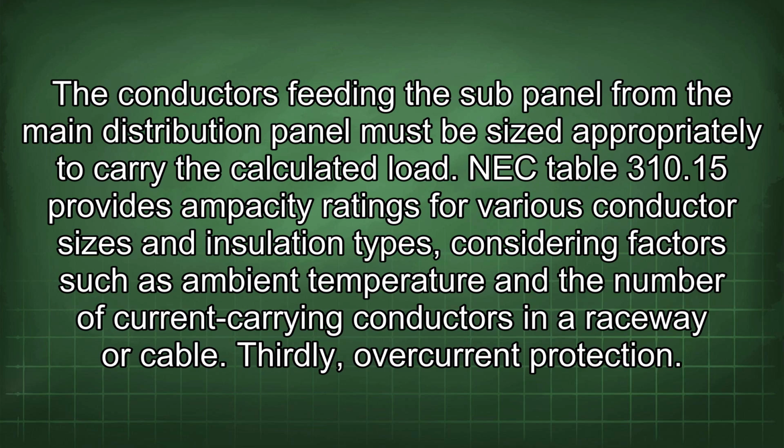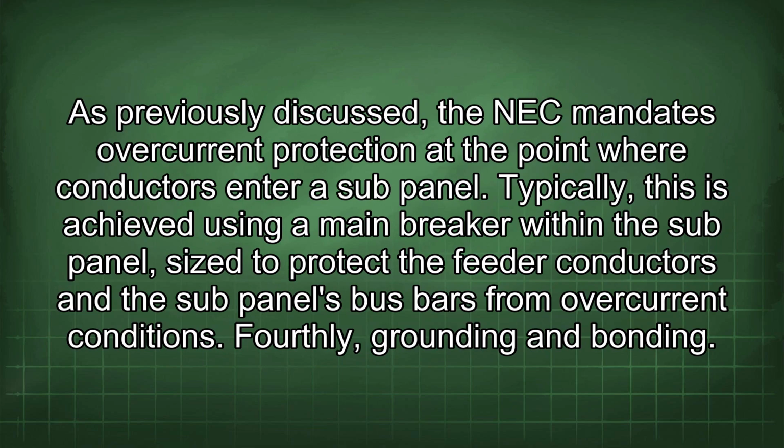Thirdly, overcurrent protection. As previously discussed, the NEC mandates overcurrent protection at the point where conductors enter a sub-panel. Typically, this is achieved using a main breaker within the sub-panel sized to protect the feeder conductors and the sub-panel's bus bars from overcurrent conditions.